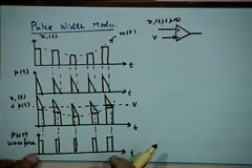Now, the amplitude of this pulse will be constant because the comparator output just produces a fixed amplitude output of some value, simply depending on whether this voltage is more than this or less than this. That is what a comparator will do, because a comparator has to tell you whether this one is larger or this one is larger, right, and this it does by generating a voltage value which is either positive, some fixed value, or 0. So, basically the comparator output will be a binary waveform, right, which is what we have drawn here, right.